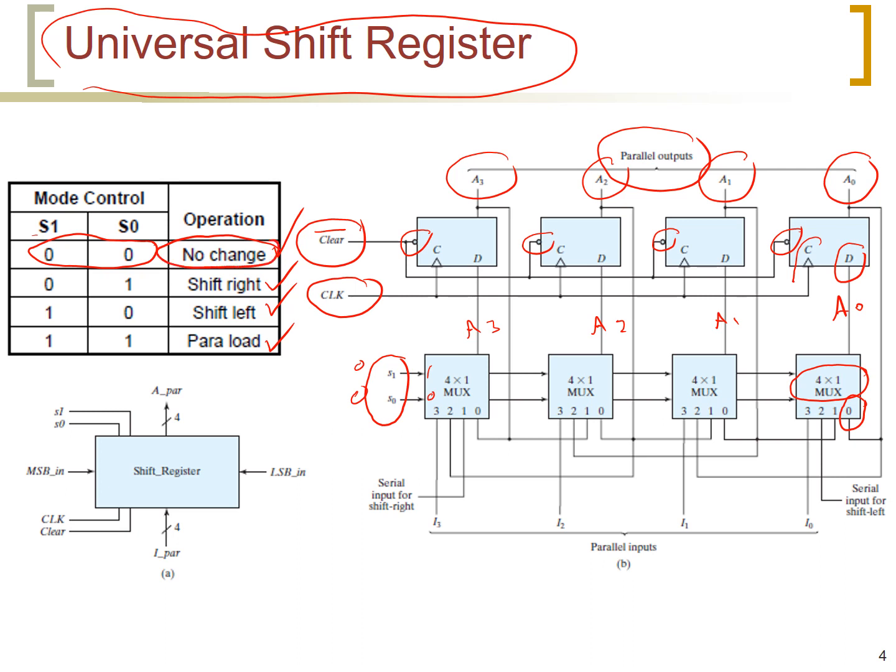Now, on the other hand, let us assume that S1 is 0 and S0 is 1. So we expect each multiplexer to pass its 1 input to its output. So we connect the multiplexer's inputs as follows. The 1 input for this multiplexer comes from A1.